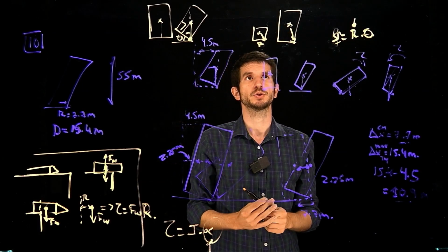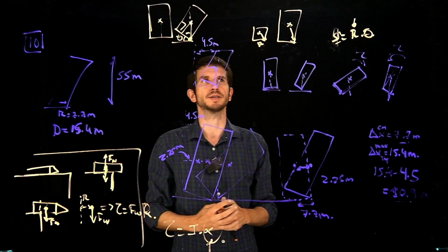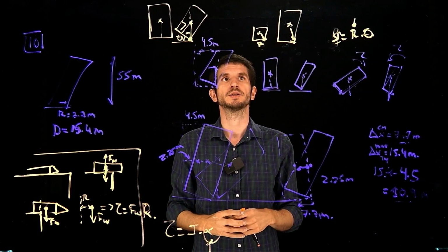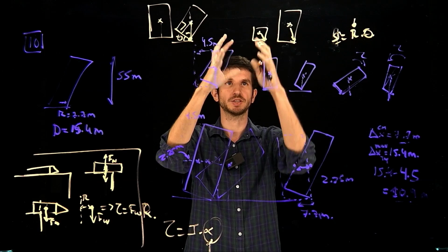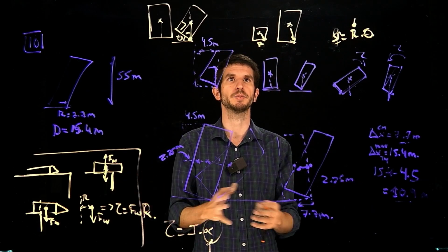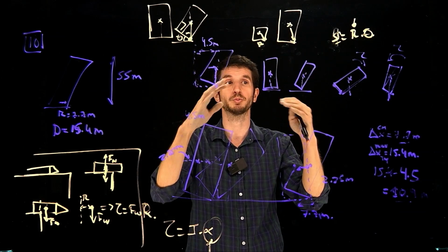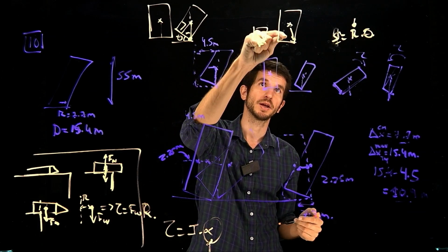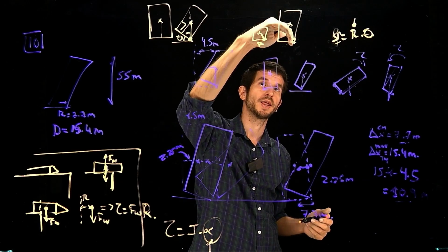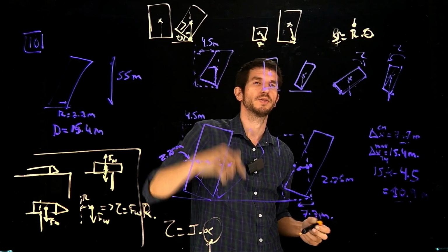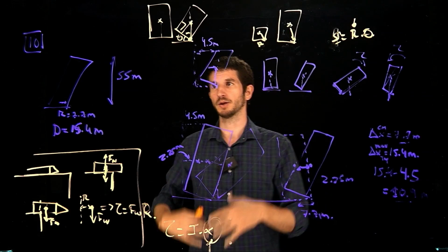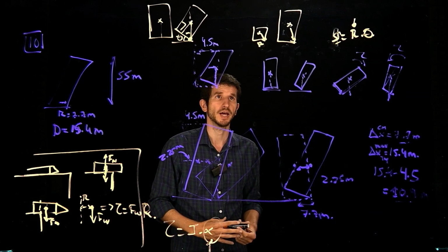So for instance, if you have a tall thing, maybe put more mass on the ground, right? So it's long, but the center of mass is not geometrically in the center, you bring it down. So you increase stability by increasing the base, so you have a larger base of support, but also by bringing down the center of mass, such that when you tilt it, the vertical line from the center of mass to the floor still falls through the base, right? So the two ways to increase stability are a larger base and bringing down the center of mass.